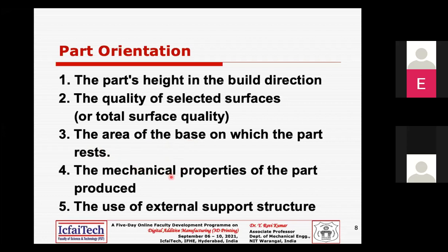You cannot anticipate the same mechanical property in all the possible orientations we are talking about. So some other time you may be looking for better mechanical property; then how do you fix your part orientation? Or maybe you may be worrying much about the support structure. Why? Because it is also equally costing you.